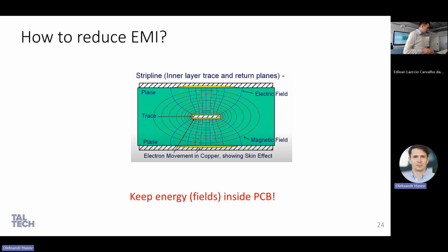The problem of conductive emission is that it's spread out mostly by harmonics, which are needed to convert your energy, but unfortunately come out of your PCB. In the ideal case, you would have a very constant current, like a straight line. But in fact, you have some frequency ripple, which actually comes out, not only through your direct conduction path, but also by parasitic capacitance and so on.